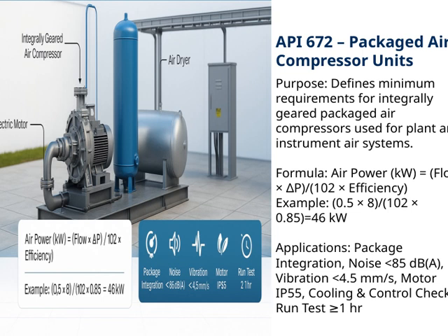The applications of these standards are quite broad. They include seamless package integration, noise levels kept below 85 decibels, vibration limits under 4.5 millimeters per second, and motor protection rated at IP55. Additionally, cooling and control systems need to be checked thoroughly, and the compressor must undergo a run test of at least 1 hour to verify performance and reliability. All these points tie back to our overall goal, ensuring that the packaged air compressor units are efficient, durable, and suitable for their intended industrial environments.